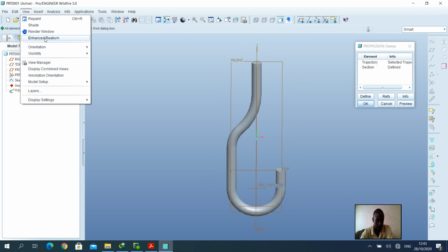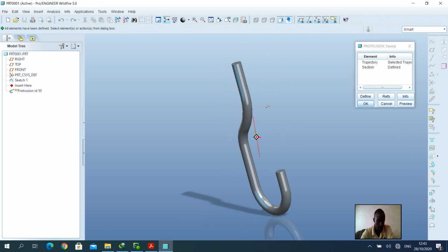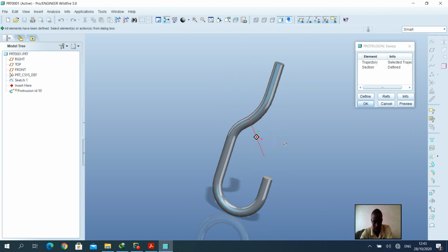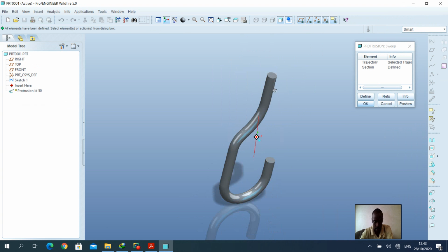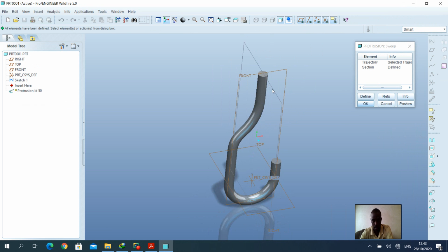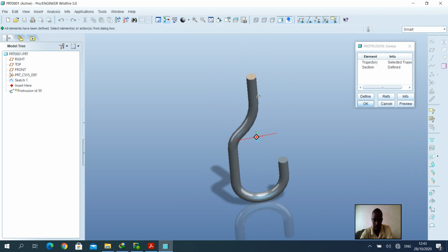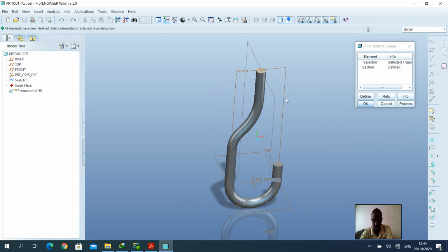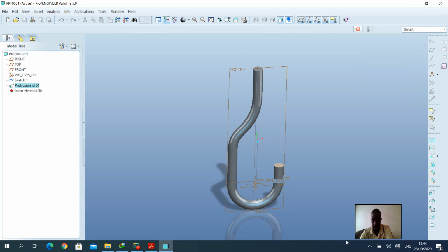Sport to enhance our realism. That's the component that we've made. Beautiful, shiny in this case. I'm happy with the board. I believe you can draw many things that have got uniform cross-section by using the sweeping operation. Pipings of different chemical processes can be made using the sweep operation, and can be made exactly in the same manner that we have made the foundation board. Alright, if you're happy with that, we click OK and we click done.